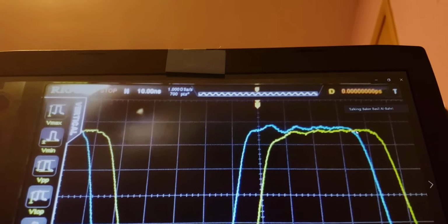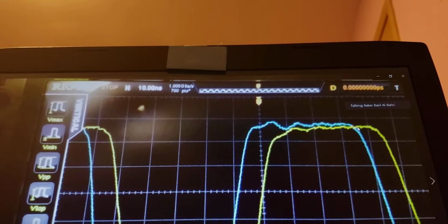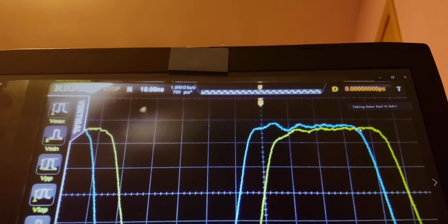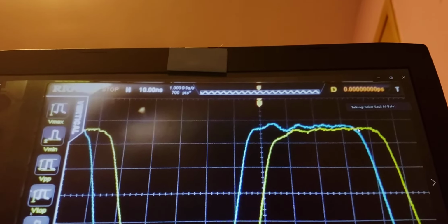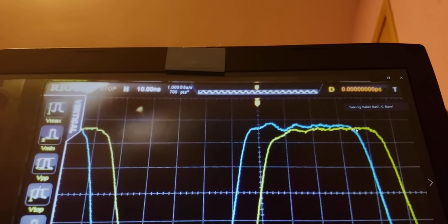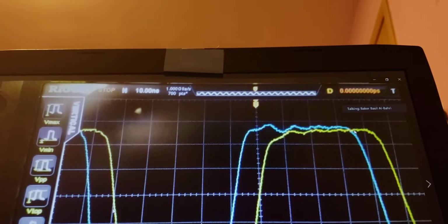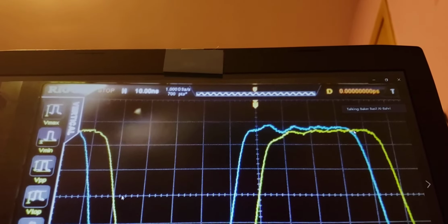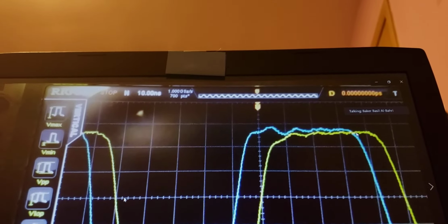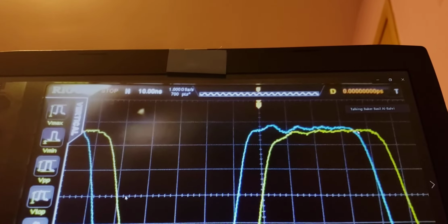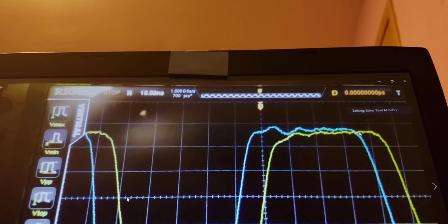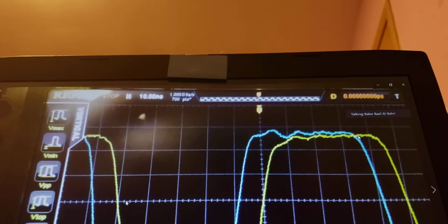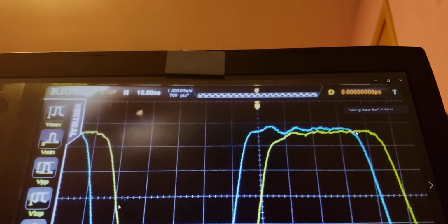The delay is here, shown as minus. We don't use the minus; it just appears when we choose the options to compute the delay in the scope, which asks whether you want it from this one to that one, or the reverse. For us, it is delay time, so the absolute value. We don't have negative delay. So the absolute value is 8.4 nanoseconds.